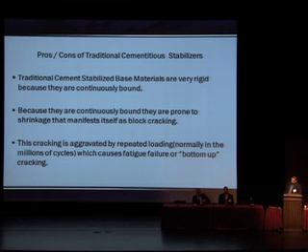Because it is a cementitious stabilizing agent, they're very rigid by nature, which tends to manifest itself because they are continuously bound. They're prone to shrinkage cracks, and that manifests itself as block cracking. And under heavy ESAL loading, they tend to fatigue out.